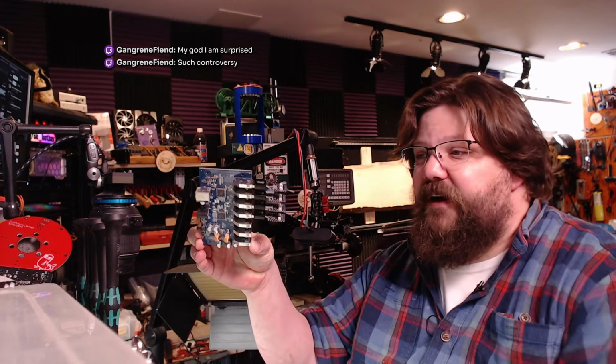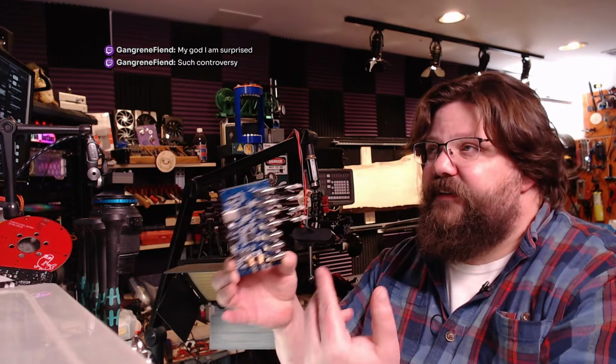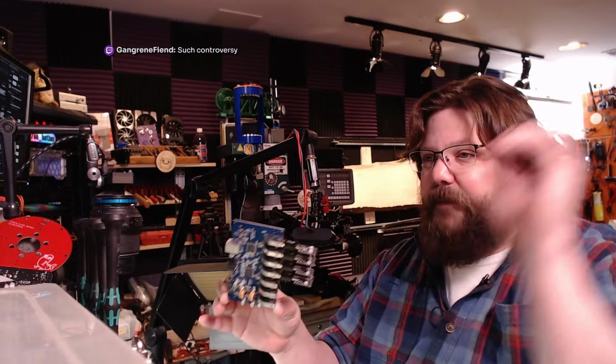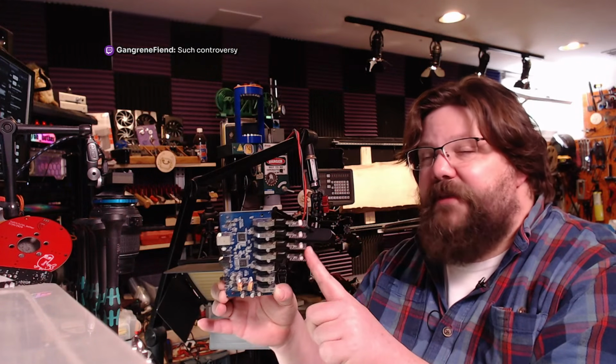But my scheme is to have everybody speaking CAN bus, even the devices that are going to translate into button pads and stuff for the computer. The way I can do that is by plugging microcontrollers into a USB hub. These microcontrollers will monitor CAN bus, but they'll also show up as like a keyboard or a mouse, a HID device to the computer. So if I split a button off from the main force feedback controller, one of these can actually take up the job of that button and press it for a different device. And that can help unbefuddle sim programs that are sort of complicated.